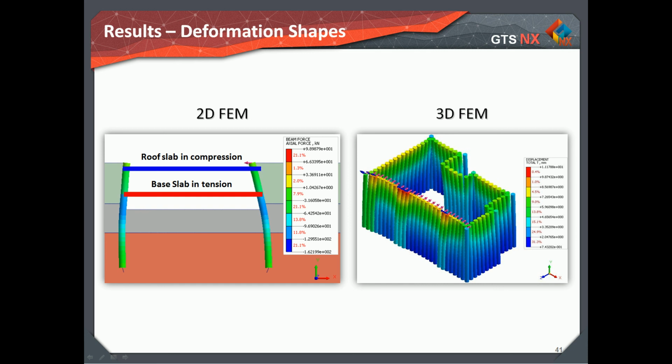Considering the cantilevered wall is already supporting the earth and column rows, that is passive resistance mobilized, once the slabs are connected, we wouldn't expect much of a load before backfill is applied, unless relaxations or stage analysis is modeled, which is not the case here.